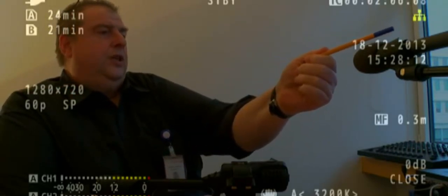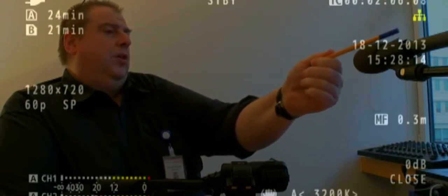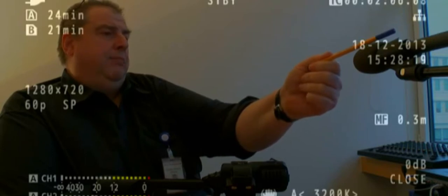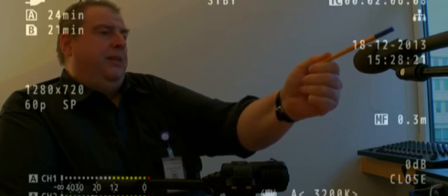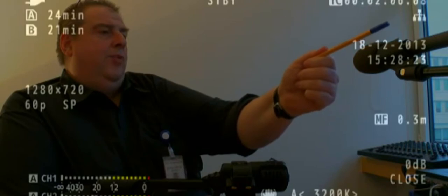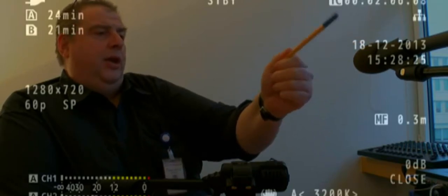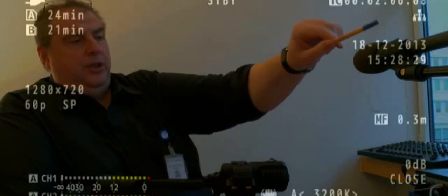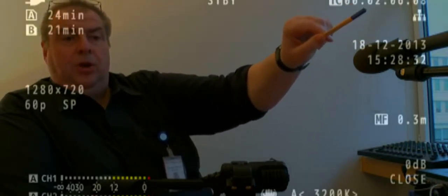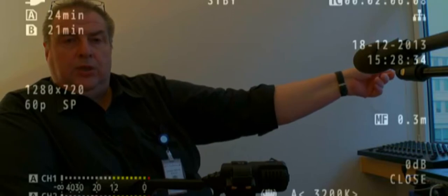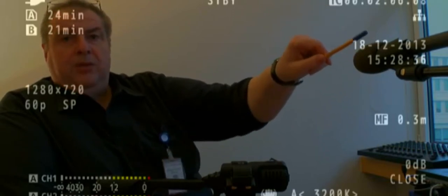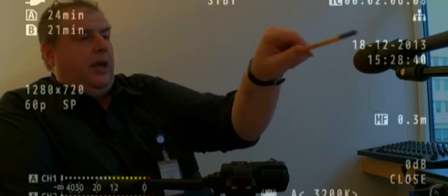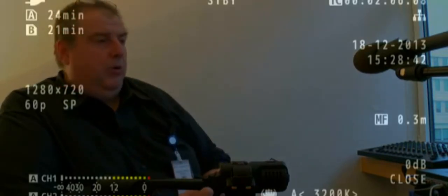So you have to see this sign here gets either yellow or white. When it's white blinking, that means there is no adapter. When it's yellow, the adapter is found. And when it gets stable white, then you have the network connection. If you want to review this information, please go to our website, go to the DSC download. There is the web seminar from a couple of weeks before, which I did for the GSM, where I go closer into this application and how it works.